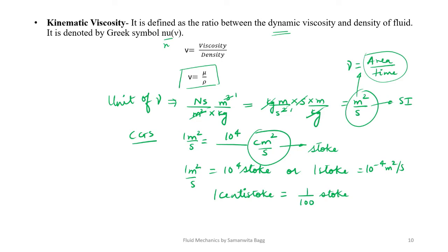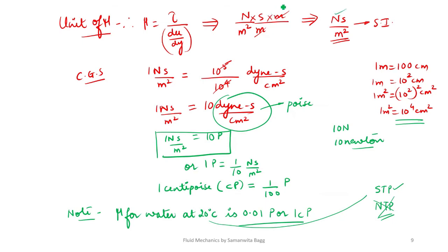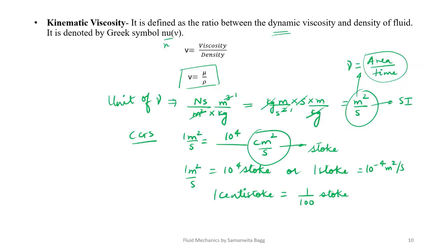So that is why you should understand that dynamic viscosity is talking about the fluid in motion. But yes, there is a term force associated over there because the unit contains the term Newton. So force comes into picture. And when I talk about kinematic, the fluid is in motion, definitely. But you would say that there is no force coming into picture.